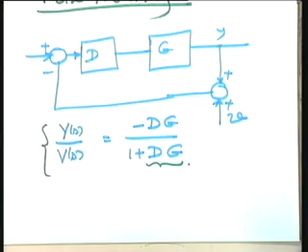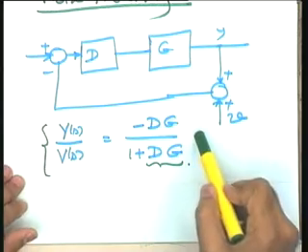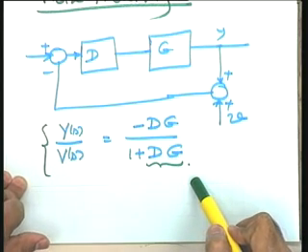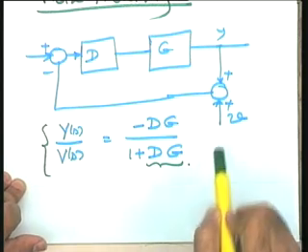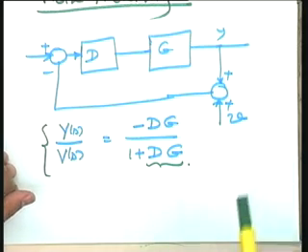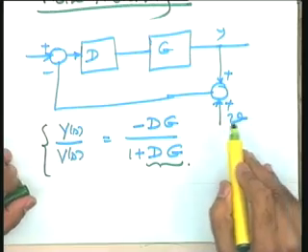This point may please be noted down, that the increase in the loop gain is creating problems as far as noise filtering characteristics are concerned. So it means again, at the sensor point you have to be extra careful. You will have to study the type of frequencies entering into the system.